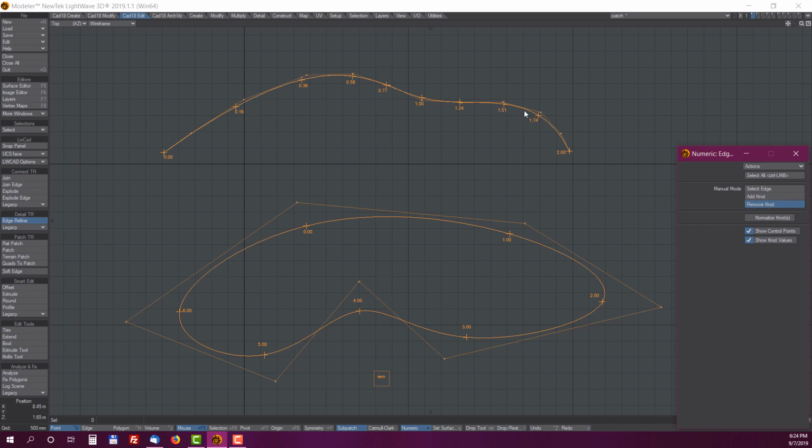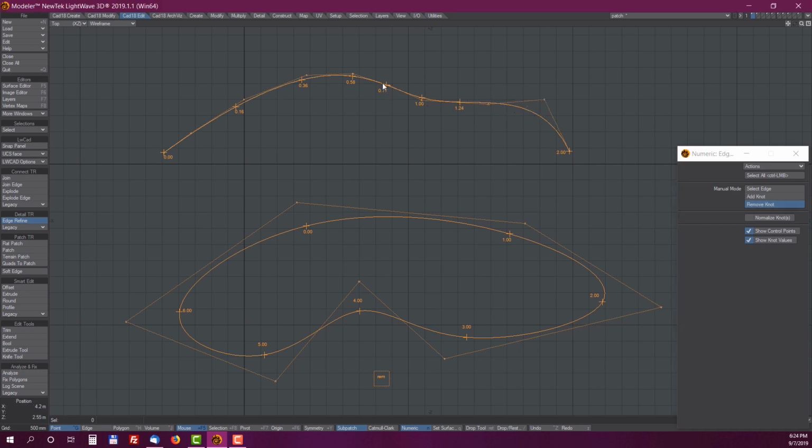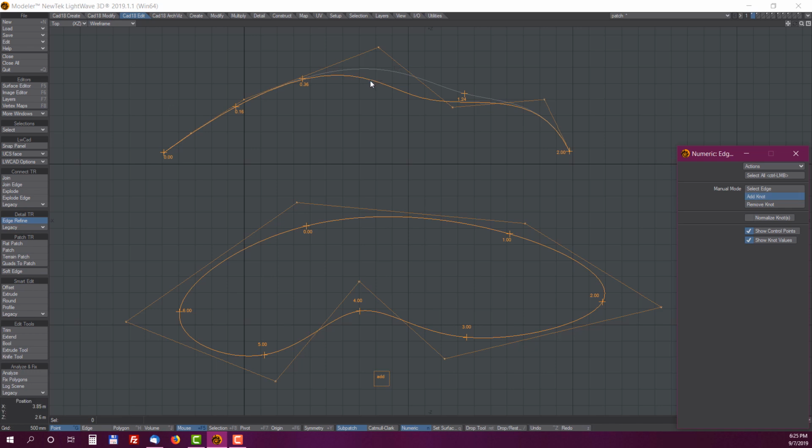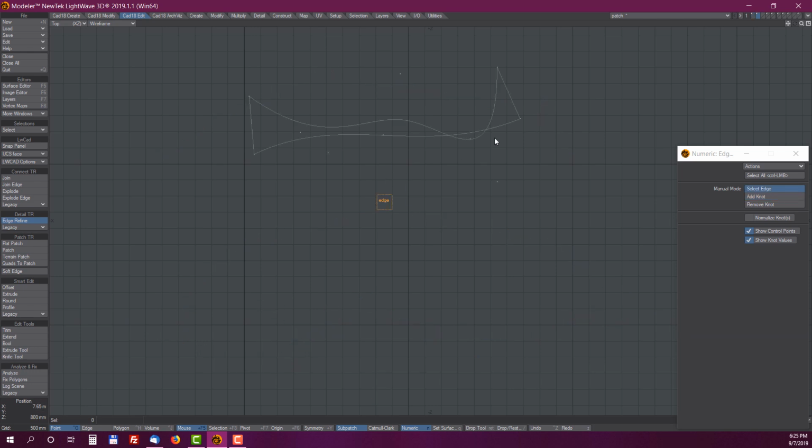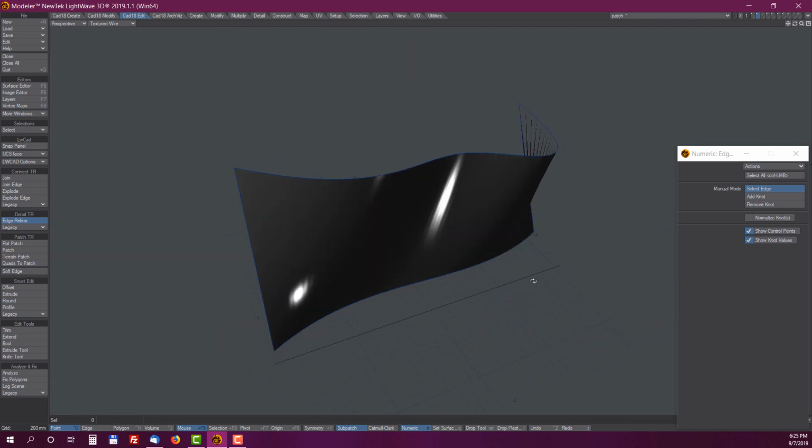You can do the reverse operation, so you can remove a node. And this operation can be destructive if you remove a significant node, which is crucial for the shape of the curve. So if I remove, let's say, this original node, you can see it changed the curve shape. So you can add more nodes on the curve without destroying shape, but removing a node can be destructive. The same works very well also on closed segments, and you can do the same operation also on NURBS surfaces.